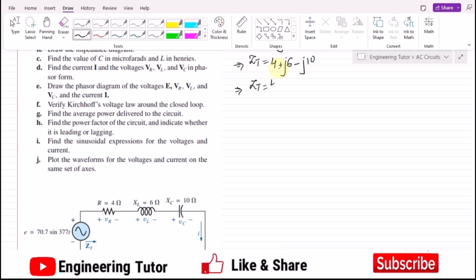Z total is equal to 4 plus j6 minus 10. So ultimately we will get Z total is equal to 4 plus j(minus 4), or Z total is equal to 4 minus j4. So that is basically the Z total.